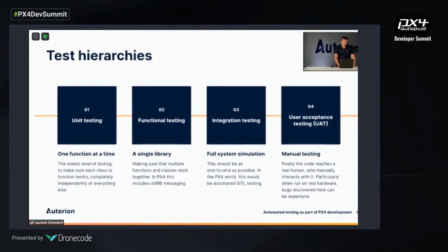The next is integration testing, and this is usually with a full system. In web development, this would be calling fake servers with your actual data, or putting your data onto a fake server and calling it and checking that it's working. In PX4, this is something like CI HIL testing, where you run your whole system in a simulation. And basically, this covers everything except for the specifics of running on the actual hardware target.